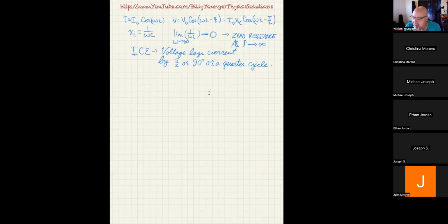V1 plus V2 plus V3 should add up to the total voltage V. That is not the case with these, because they're not necessarily all in phase. And in fact, you'll quite normally get voltage adding up to greater than the peak voltage or greater than the RMS voltage, whichever one you want to do.